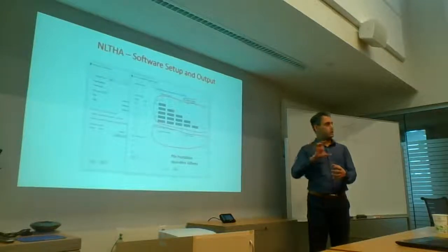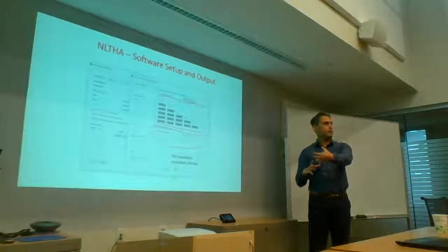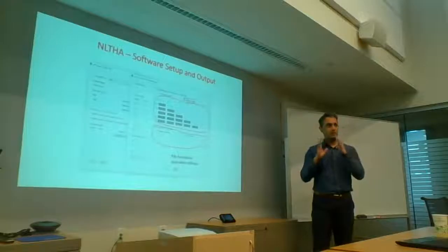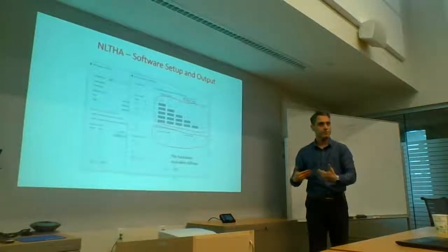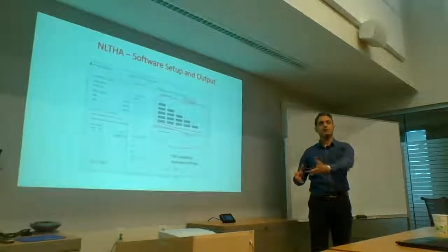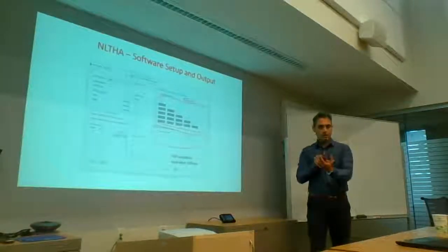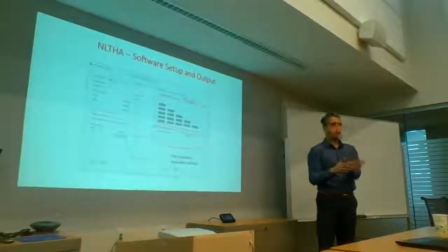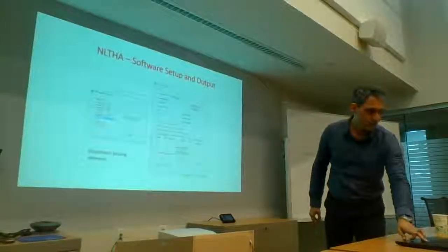Like if you pushed your foundation one way, it might rotate in another degree of freedom. So any of the diagonal terms are basically just, you apply a force this way and the resistance is in the same direction. You apply a force this way, the resistance is in the same direction. You apply a moment, there's a rotational restraint. But with some of them, they found that if you activated one degree of freedom, the other degree of freedom got activated. So those are the off diagonal terms. So we got those in there.